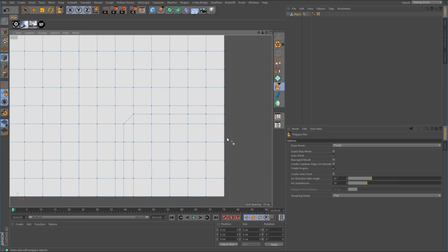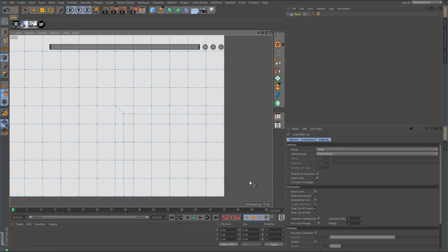Now we've created a little bit of a problem here. You can see that there is a triangle there. So we just need to go up here to this corner point and make a cut to about there, and we'll just push that back into place like that. And now we have solved the issue with the triangle. We now have quads there, but not only that, we have now created the area where the cut will be redirected.